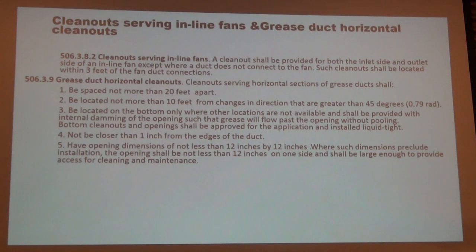Mark, how do they do it? Normally, you cut the same materials as the jackets, like a blanket. You put it in there where the stick pins are on the cap itself. And then you put a galvanized plate on the outside with long butterfly nuts. So it has like a system. It will be probably 10 to 12 inches thick, because you have to double up and then galvanize.